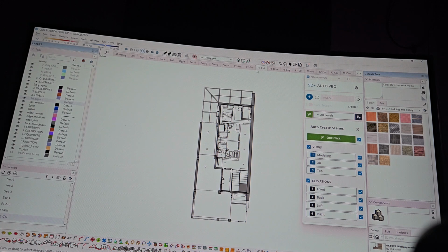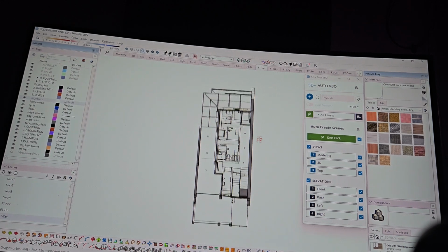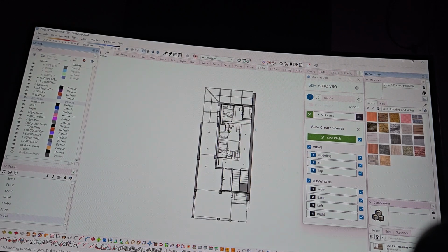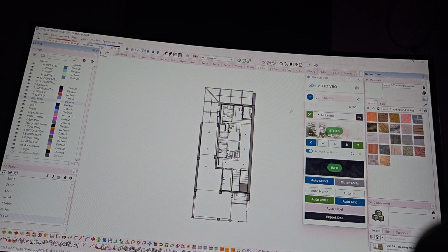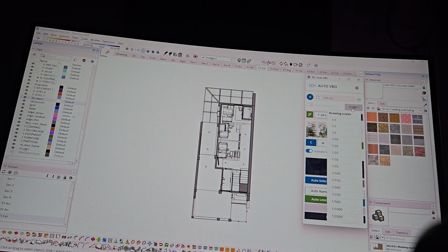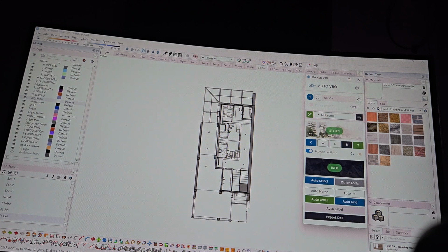I have another method, which is my reflected ceiling plan method from the top view, if you check our other tutorials. However, let me analyze if there's a rotate tool that can be done here. Preview paper. This one actually has a scale that says 1:100. If I try 1:75, this could actually scale the viewport of the layout paper. That's why we also have a viewport tag somewhere here.